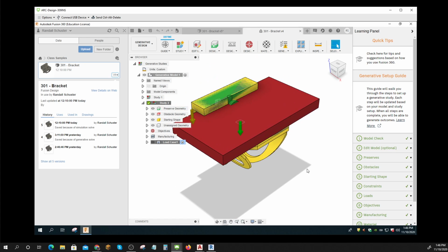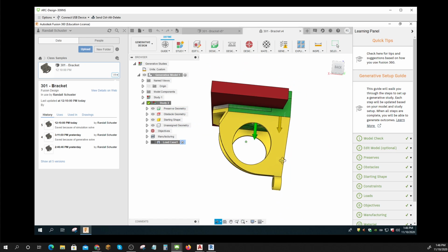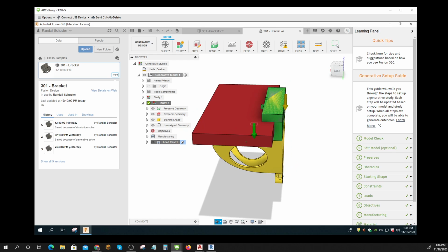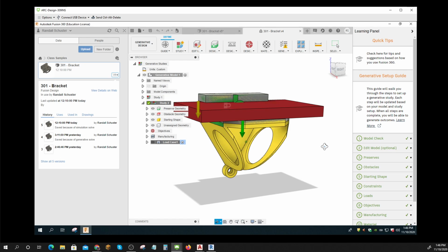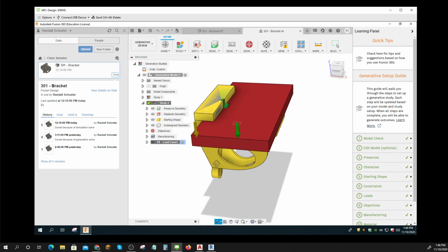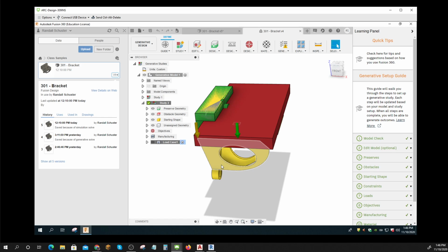It's just rectangles and stuff. If you want to play around with that, you can. Maybe not in this module, but in the next module. But I wanted to let you know what tools are available to you. And look, this is just the rectangle command. Most, I use the rectangle and the line and the circle command. That's all I used in this. And then press pull. So if you've done any 3D modeling, you're able to do this.